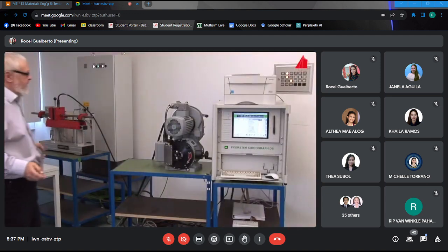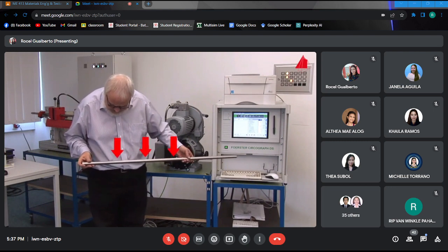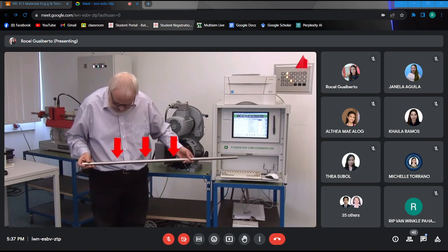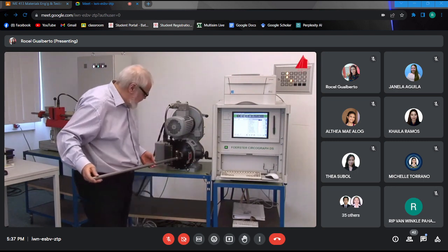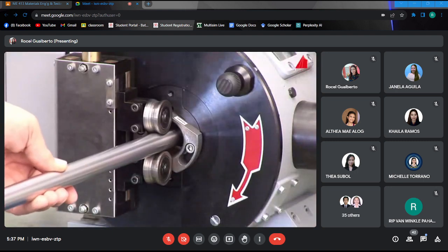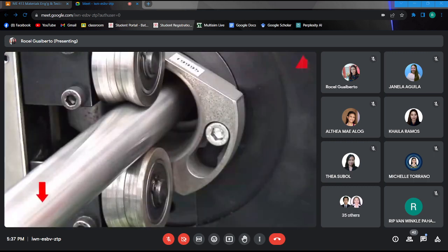This version of eddy current testing is also well suited for mechanization. 3 very fine saw cuts with varying depths have been machined into this massive cylindrical rod in longitudinal direction. The rod is again made of an austenitic steel. The materials tester pushes the test piece with constant speed into the machine, so that the saw cuts pass through the actual test area.